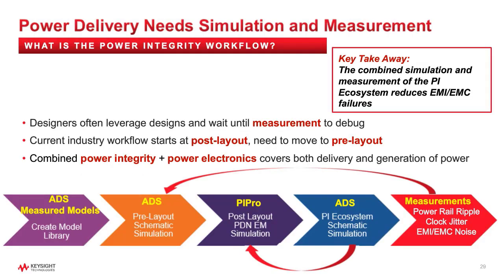Finally, let's take a look at the complete power integrity workflow. The full power integrity workflow might look more like what is shown here. Designers start with good models of the VRM, the decoupling capacitors, and the load. Often, the best models are measure-based models, such as a state space average model of the VRM, or a measured S-parameter of the capacitor. Next, pre-layout investigations like the one we just did enable the designer to understand the challenges and provide layout guidelines. Once the PCB layout is done, a post-layout full EM simulation can be done, and then the result used to optimize the location and values of the decoupling capacitors.